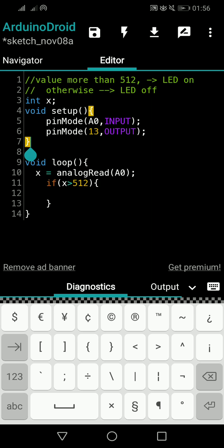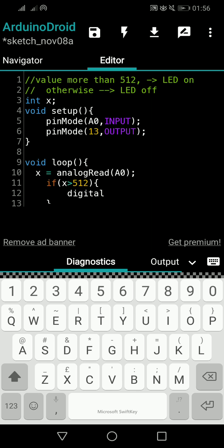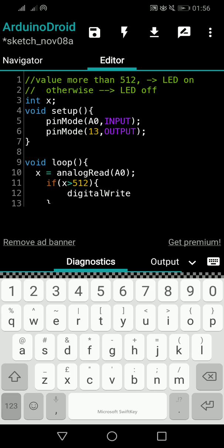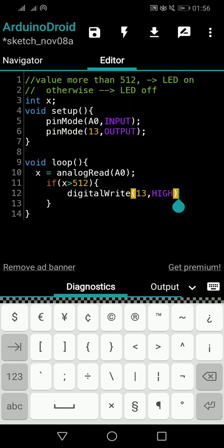So how to switch on that LED number 13? We have the keyword for that called digitalWrite. You understand what I'm talking about? DigitalWrite. So now we are beginning to combine the codes that we learned to create a full complete system. digitalWrite 13 what? Sorry, I got confused. 13 HIGH. That means 13 is on. That means 5 volts is giving us an output on pin number 13.